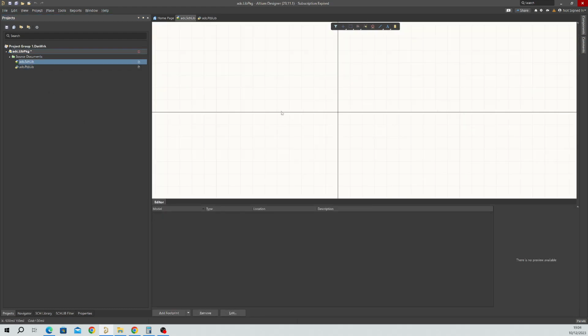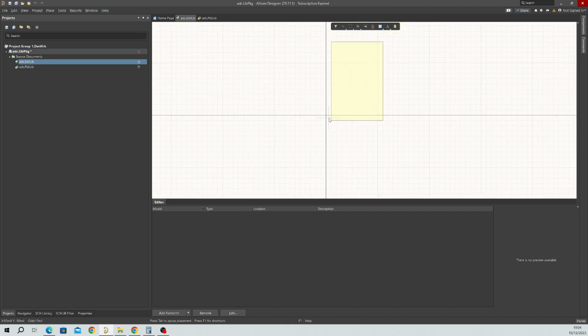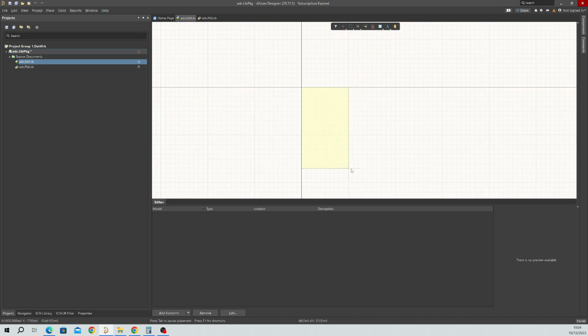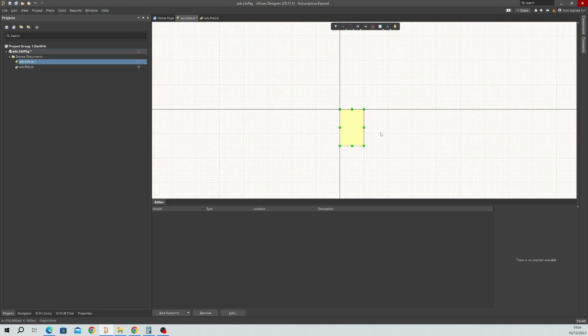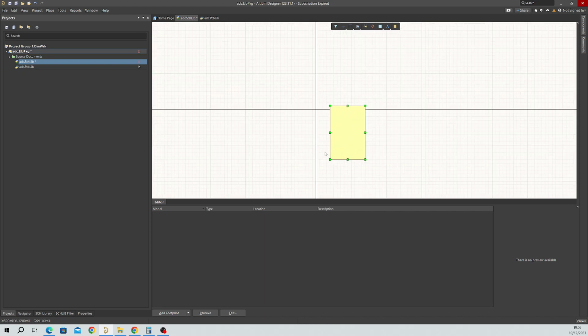Now, an ADC. Well, it starts with a body. So here, where it's got a line, placed line, if you right click, you can draw a rectangle. Start always at the middle of the cross and then draw down. The middle of the cross is the anchor point when placing parts, typically. So, for instance, if you created a rectangle over there, when you placed it, your cursor would be here, but your part would be all over here. So that's not what you want. So aim for the center.